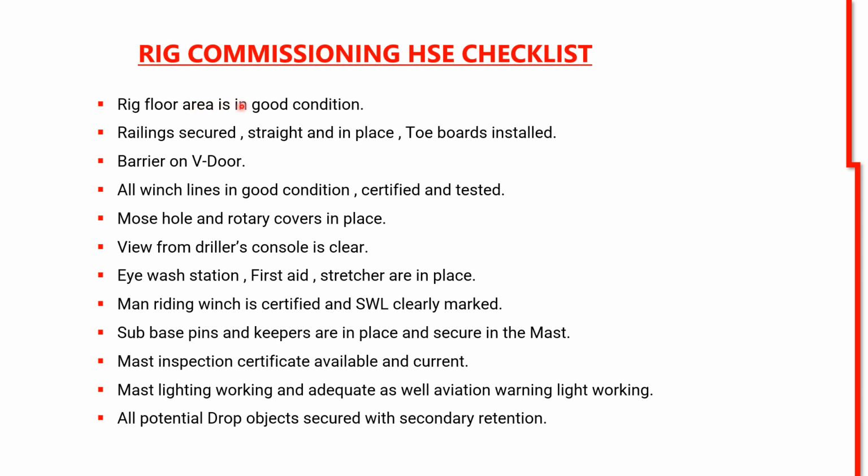And all the holes which are not being used at the time should be covered. For example, the mouse hole, and if it is a Kelly drive rig, there should be a rat hole. If that is not being used, it should be covered. The surface should also have no chance for slips. And the plates used on the floor should be stable, strong enough, and fitted well.